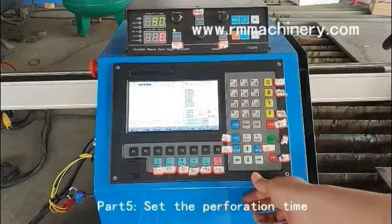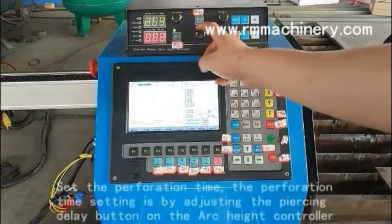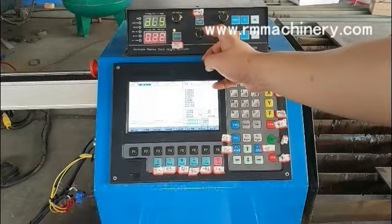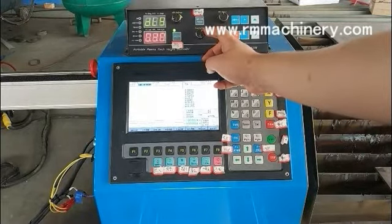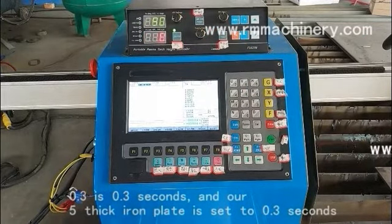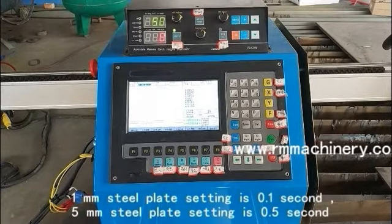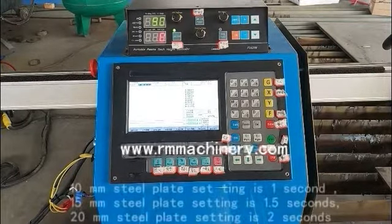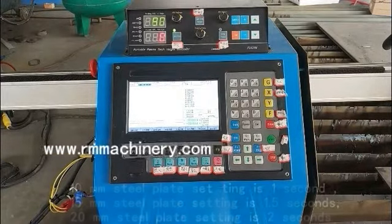Set the perforation time. The perforation time is set by adjusting the piercing delay button on the arc height controller. 0.3 is 0.3 seconds, and our 5 mm thick iron plate is set to 0.3 seconds. 1 mm steel plate setting is 0.1 second, 5 mm steel plate setting is 0.5 second. 10 mm steel plate setting is 1 second, 15 mm steel plate setting is 1.5 seconds.